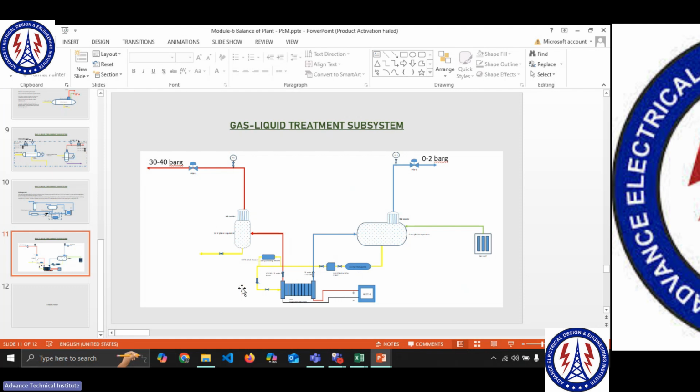Why do you need that pressure difference? Because you need to push it into the electrolyzer. In the electrolyzer, you will have multiple concave convex structures that we talked about in our first classes. Then you need to get this back into a separator. So for that, you will need some pressure difference of about 2.5 to 3 bar. So here, if it is 27, output will be at 31. Okay, clear? Yeah, clear.